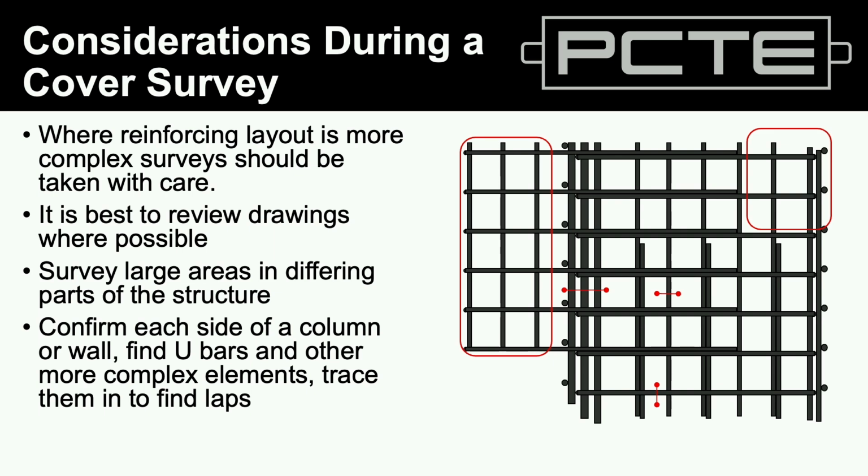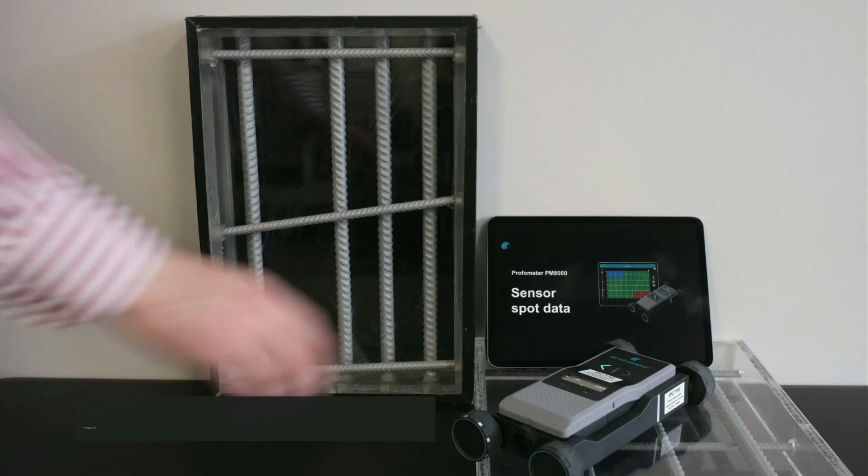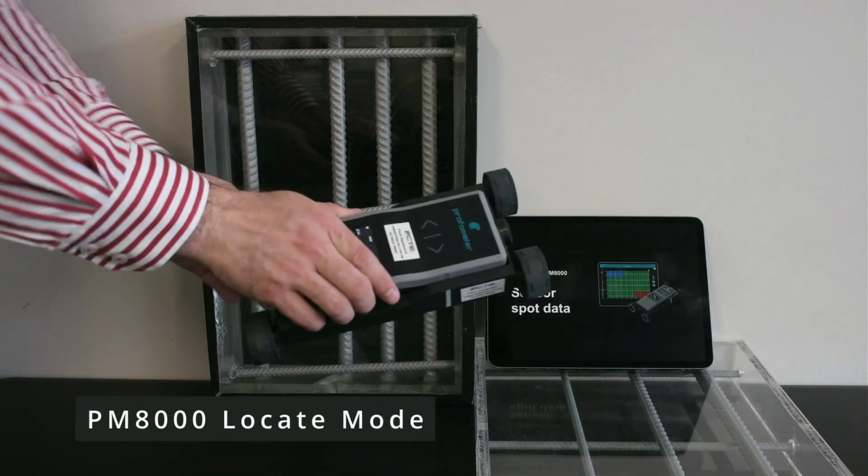And again, I know the question is sometimes, well, we just don't have that information. Well, then it needs to be fed back to your client. If we can't do some destructive investigation, or you don't have some records to give us, or we can't get the GPR scanner out and increase the scope of the job, your depth precision on a quick cover meter check isn't going to be there. Just manage expectations. Now, let's look at a cover meter in action.